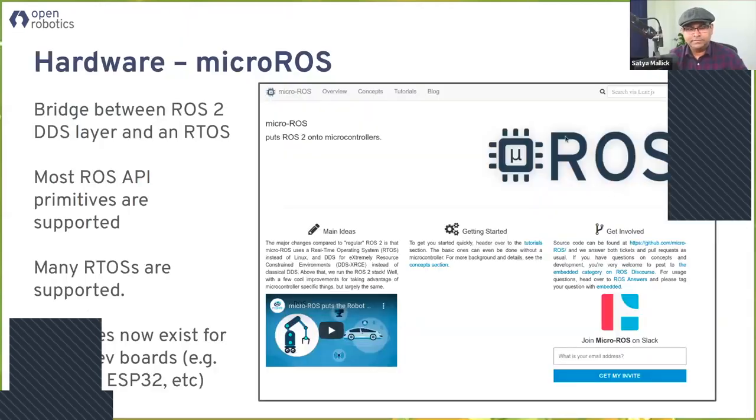The mezzanine, the second floor? Yeah, the second floor, right? The second and third layer. And the reason we did this is that there's this developing community in ROS called micro ROS, and this is essentially a subset of ROS 2 that's built for microcontrollers. Think your Arduino or your Teensy or your ESP32s, all of those microprocessors, you can basically install a couple flavors of a real-time operating system, run micro ROS, and then have the thing natively talk ROS back and forth.